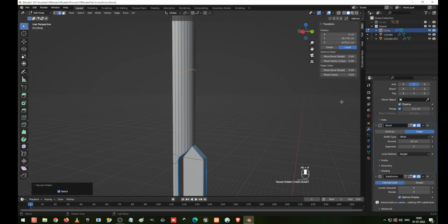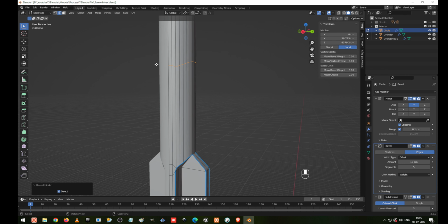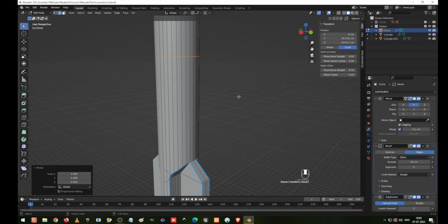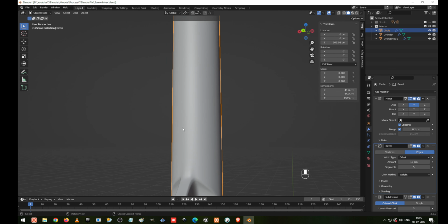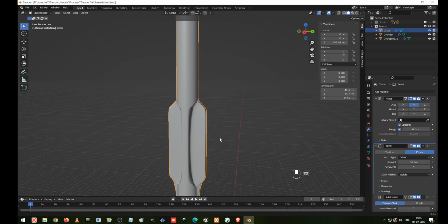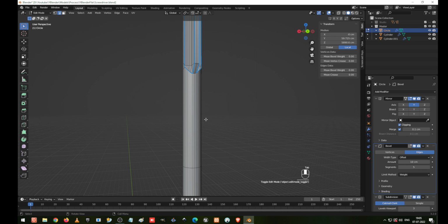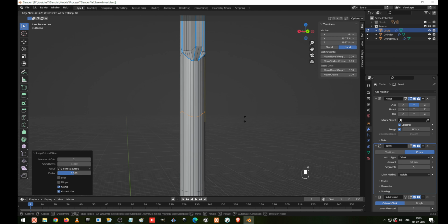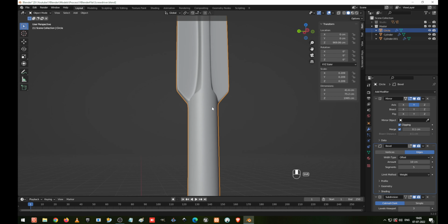I make it Alt H. So I'll go to this option. Okay. Now I created one edge loop. Scale it in z-axis 0 and GZ to move down. So now everything is fine. Same way we can do it. Create one edge loop and double G to move towards here, and we can see how it looks. Yeah.